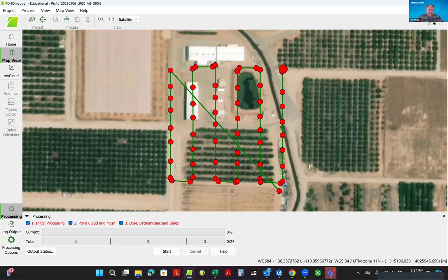If I click on one of the images, it's going to snap to it. I can left click around this just to process the footprint. Then I right click to close my polygon. This is actually just a time saver when doing the same thing in, say, ArcGIS Pro at a later time, because then your products will already have a nice clean edge.